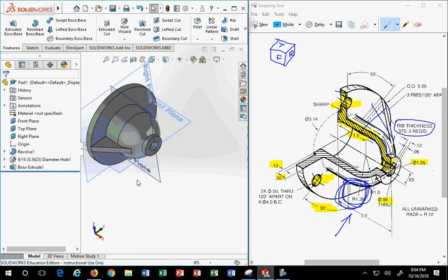If the radius isn't critical, you're going to sand it down, aren't you? Or a grinder or something. Right. But let's say the radius must be perfect. So now you've got to put it on the lathe, make sure it's centered. Probably won't even start this way, right? You'd start with a whole different object.